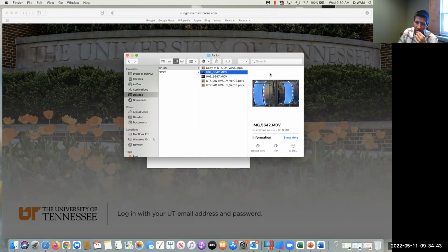Okay. One quick comment on the nuclear stuff, and again, it might be a nice coincidence. I'm sure you're way more familiar with it than I am: the ANSI N13.1. The specific standard is around duct monitoring. When you have a single point probe that's monitoring either your discharge from labs or into your control rooms, that typically requires you to have a certain amount of mixing, and there's a homogeneity spec there in case you have a pinhole in a filter or something.